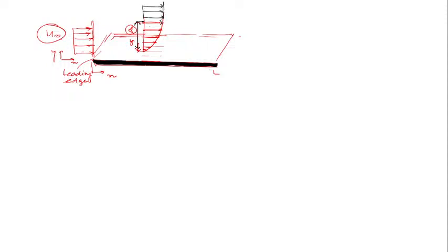So only delta is important for our consideration from a study point of view. Why? Because there is no resistance beyond that. All the resistance is only up to delta, because all the gradient in the velocity is here. Delta is where the velocity is close to 99% of the upstream velocity. This thickness is called the boundary layer thickness. Ready? Clear?